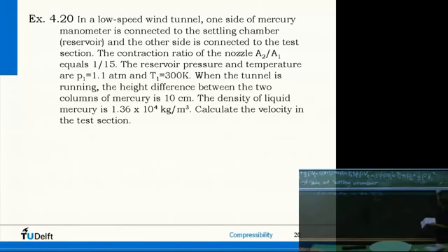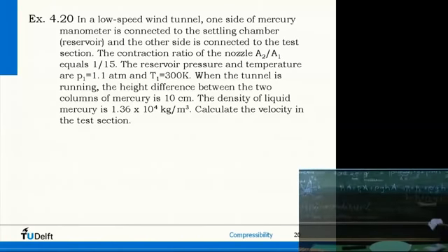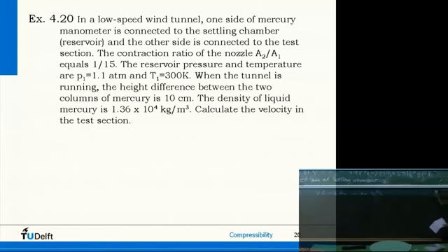And then we have it. So the steps we went through: the manometer gives us the pressure difference. Bernoulli relates the pressure difference to the speed squared. Density from location 1, because we have pressures and temperatures there, from the equation of state. And then finally we use the continuity equation: V1 A1 is V2 A2.